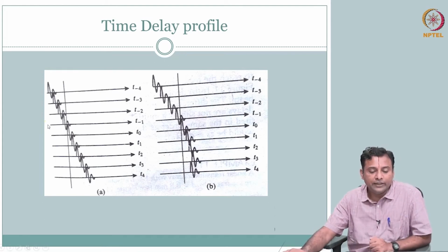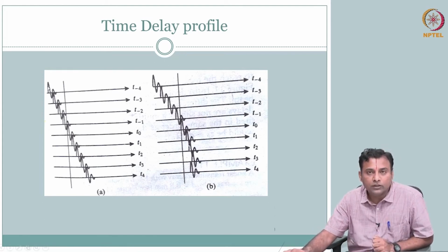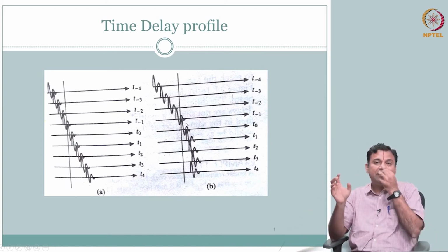Okay. So, you can see that you can realize both steering and focusing by combining the time delays, right. Steering alone is only linear with respect to each of the elements, the time delays are just multiplied, right, whereas here that is not the case. Okay. So, this is for transmit.